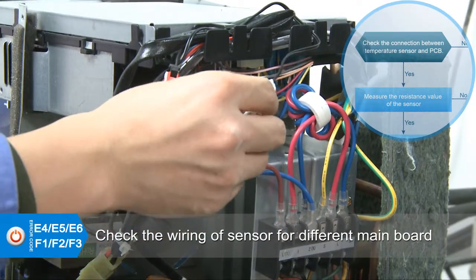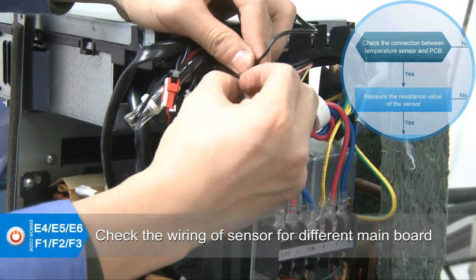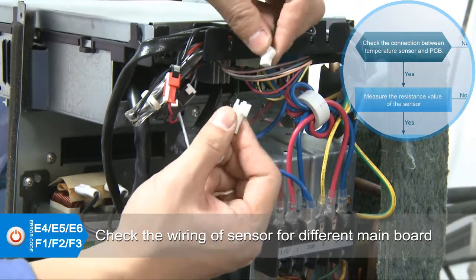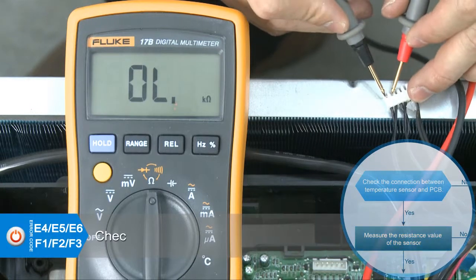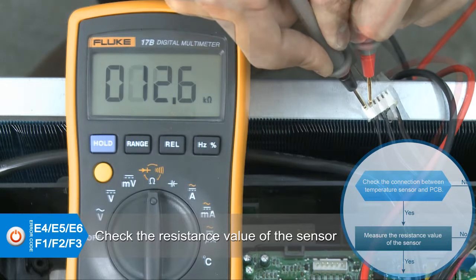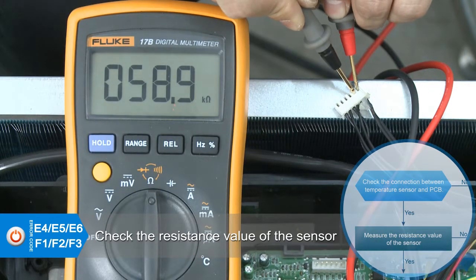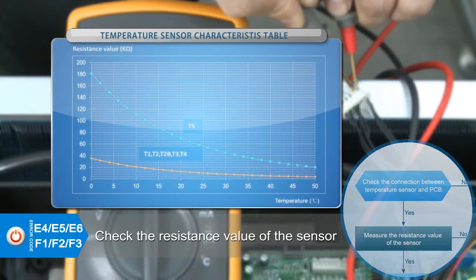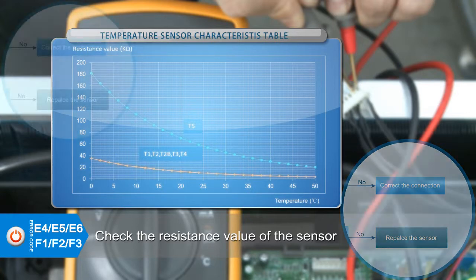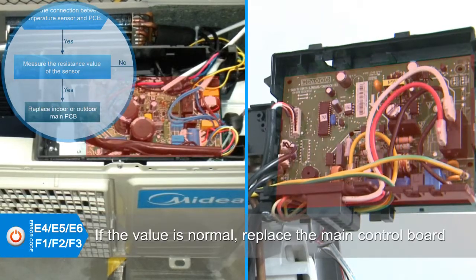If the wiring of the sensor is correct, check the resistance value of the sensor. Remove the protective buckle. Pull out the plug. Measure the resistance value of the T3, T4, T5 sensors. The resistance value refers to the characteristic table. If the value is abnormal, replace the sensor. If the resistance value is normal, replace the main control board.